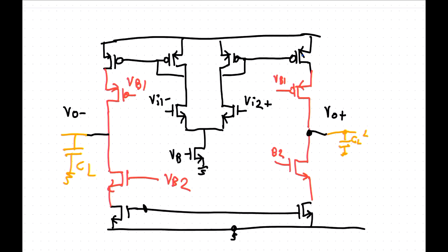Now we're left with something though, because at the moment I've been very naughty, because I have left that gate disconnected. If I ever see a circuit like that with a gate disconnected in any of the assessment material, I know you haven't done your simulation properly, because this doesn't work. You can never ever do that. You cannot leave a gate disconnected. So we do need it for something.